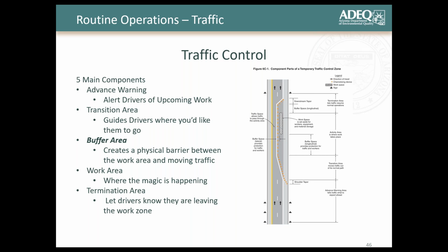Of course, the fourth main component is the work area. This is where the magic is happening. This is where you're doing what you need to do. And of course, another important area that sometimes gets ignored is the termination area. You've got to let the drivers know, hey, you're out of this work zone. You're good to go. Go ahead and transition into your lane and follow normal traffic rules.